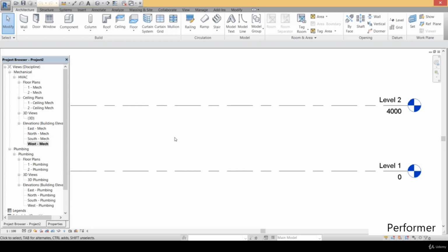specifications. For example, the architect specifies the height of the suspended ceiling, as this is his decision, as the suspended ceiling may be about 60 centimeters or 80 centimeters from the main concrete ceiling. So according to that information, we start our HVAC design. And to insert the architectural CAD layout, we easily press on the Insert tab. So let's go to the Insert tab here.